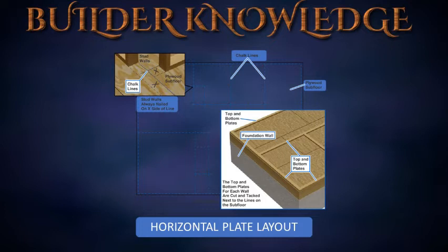You will cut the top and bottom plates to length and tack them to the lines. You will mark plates for corner posts and regular studs, as well as trimmer studs and cripple studs for rough openings. Lay out studs for the first exterior wall.